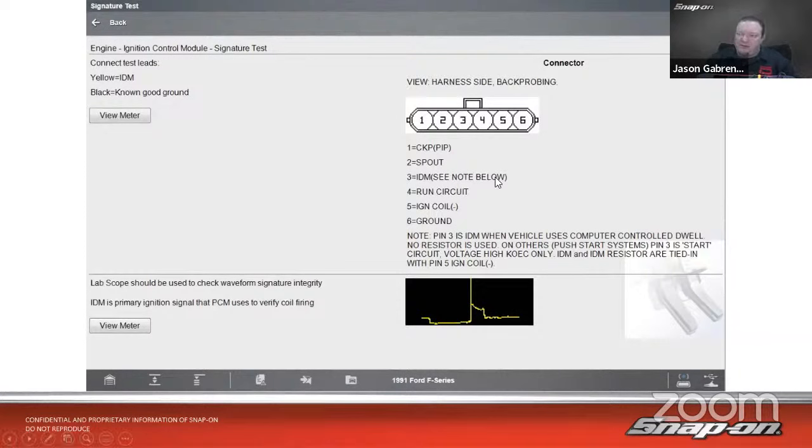And well, we said, okay, well, it's stalling and it's randomly stalling. It's not just at a time. It could be running for a minute, could be running for an hour, could be running for 20 minutes, could be 30 seconds. Doesn't matter. It'll stall when it wants to. So we said, all right, so we got to figure out, why is it stalling? What signal goes missing? So this is really where a scope comes in handy.